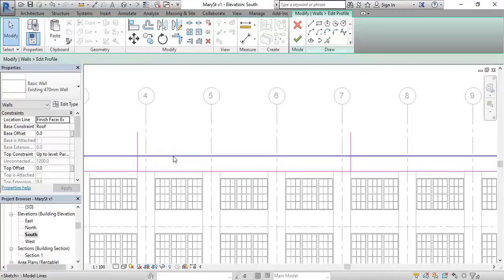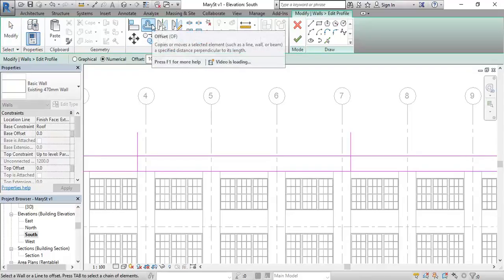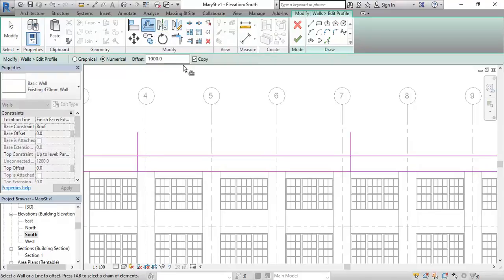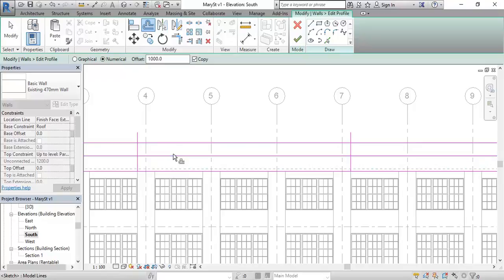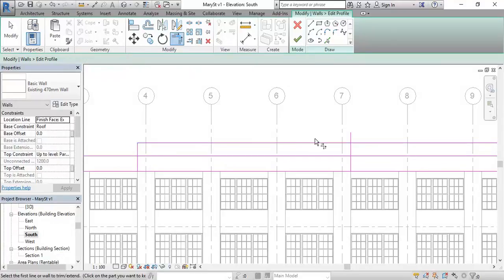It's really just a decorative element. You're not really going to be making any changes to the size anyway, so I'm going to use the offset tool, because I know, apart from anything else, it is set to a metre by default, so I can simply pick my line below, offset above, and I'll maybe trim straight away so that it's clear what I'm trying to draw.